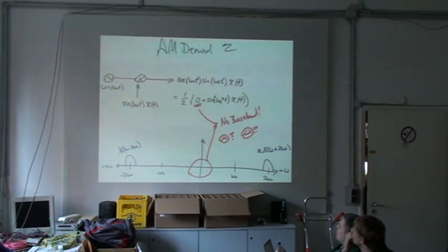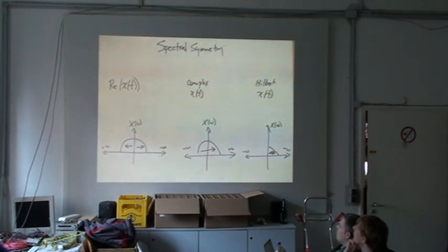This really complicates things. And then you realize, no, this is a huge opportunity, because I can modulate another information signal on this quadrature carrier, and I can send two information signals using the same system. And they'll be orthogonal to each other. One will just disappear when you look at the other.